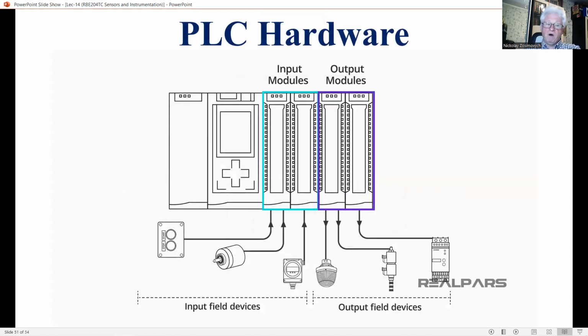As noted before, a PLC is a digital computer that is dedicated to performing discrete state control tasks. A typical PLC consists of a microprocessor, RAM and ROM memory units, and interface hardware, all interconnected through a suitable bus structure. In addition, there will be a keyboard, a display screen, and other common peripherals.